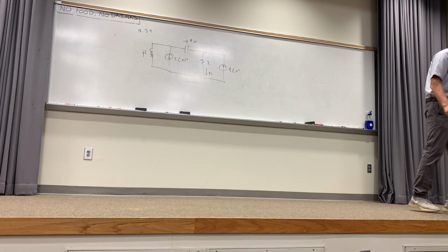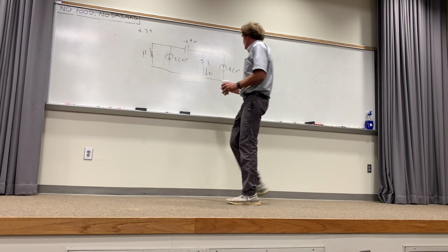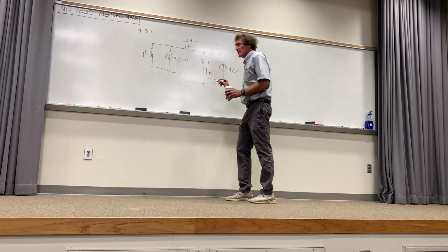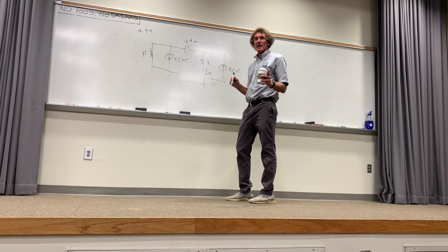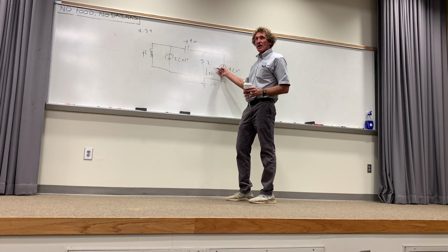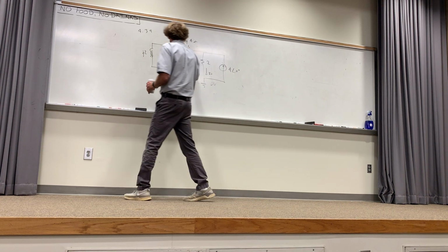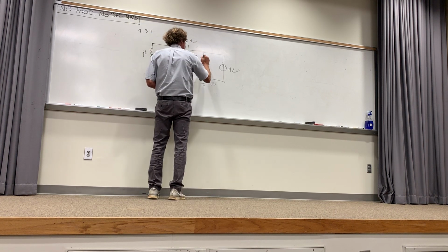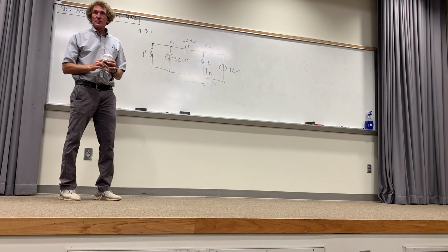All right, this is the problem set up, and even in the problem, he shows you the symbol for a ground. It's like that, and that's 0 volts. So he's telling you that's where the ground is, which is nice of him. Now, when you have that, he's after this current I0, right? But really, he asks for you to do it nodal, right? Use nodal analysis. So there's 2 nodes. Here's the first, and we just put an unknown voltage V1 there. Here's the second. And we can put V2 here. So now I've got my unknown voltages.